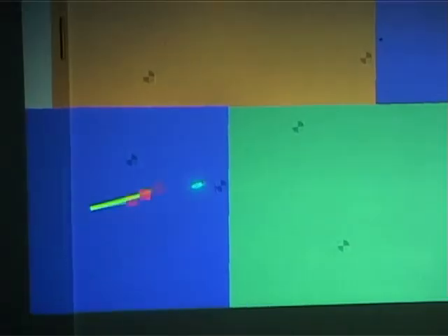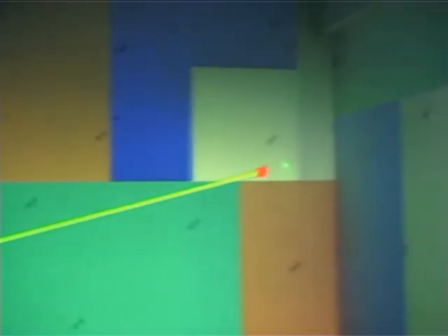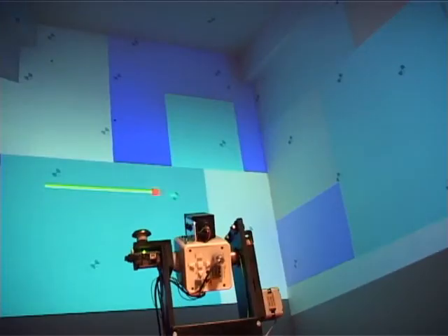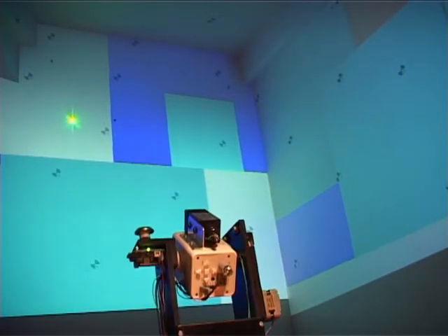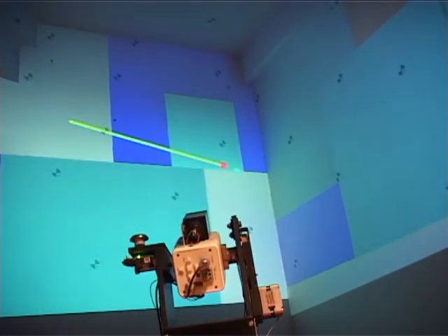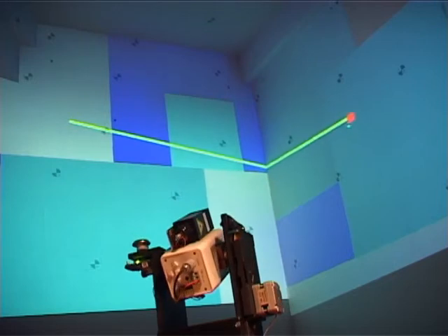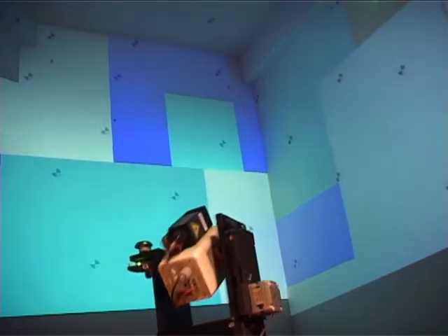If visible in the detail camera, the position of the laser spot can be estimated. If the spot is lost, the context camera delivers information for realigning the detail camera. There are 2 reasons when this can happen. Either the laser pointer is turned off and turned on again, pointing somewhere outside the current perspective of the detail camera, or the movement of the laser spot is too fast for stepper motors and detail camera to track.